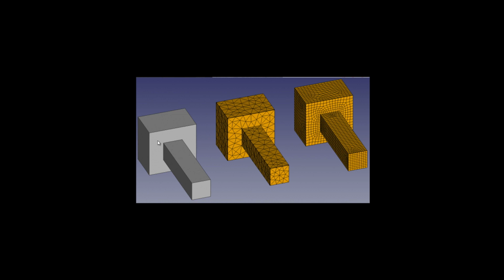which means we need to use the CAD geometry so that we get solid elements that are of a specific size that we can control, and where the aspect ratio isn't too messed up. All sides of the element need to be the same. That's what we strive after. Of course, that's not always manageable given the geometry. Well, in this case, it's pretty simple, so most of these individual elements have pretty much the same sort of side length. But in general, it's not always possible.